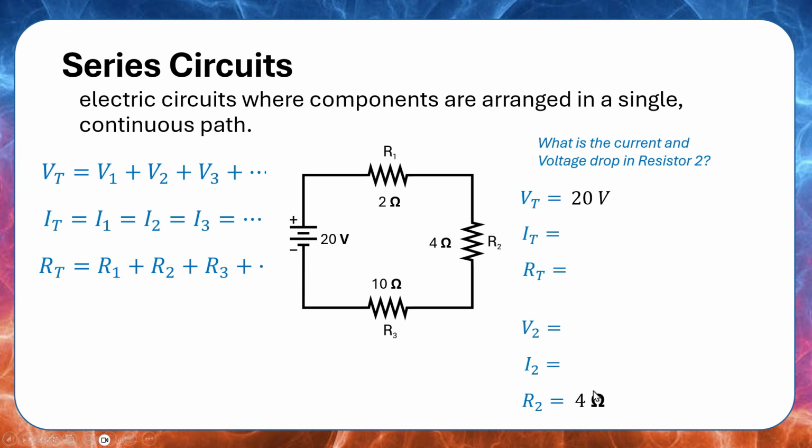But the question is, which of the other variables can we get out of the givens? The total resistance, of course. And in series, the total resistance is just the sum of all the resistors. So we have all the resistances here in our series. You just need to add them up: 2 plus 4 plus 10. That's 16 ohms. So that's our total resistance, and that's it.